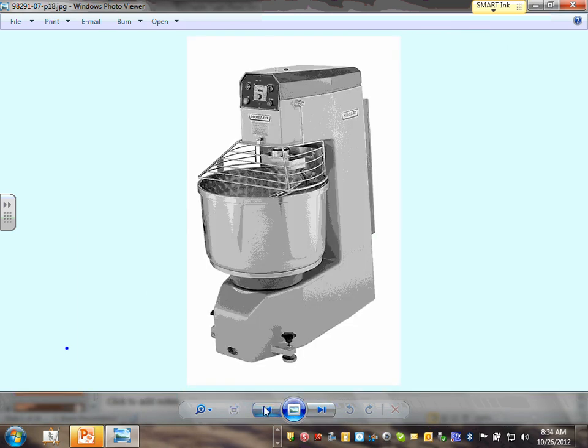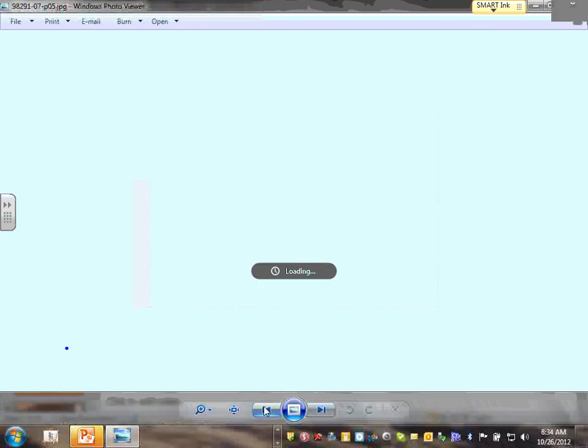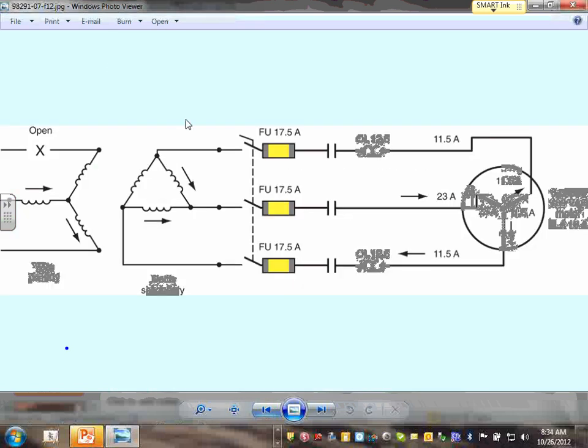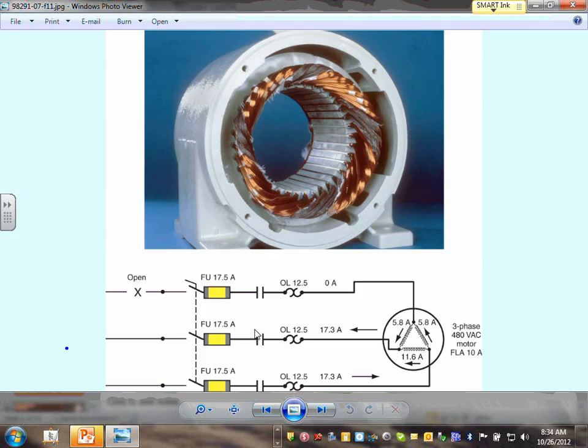Any comments, guys? Good one. Any comments, any questions about that? I want to go back into, okay. I can't emphasize, guys, I know you're not engineers, but I can't emphasize the single phasing on motors. It's so important. Sizing the overload based on what I told you is very important, especially in a three-phase motor, because of single phasing.